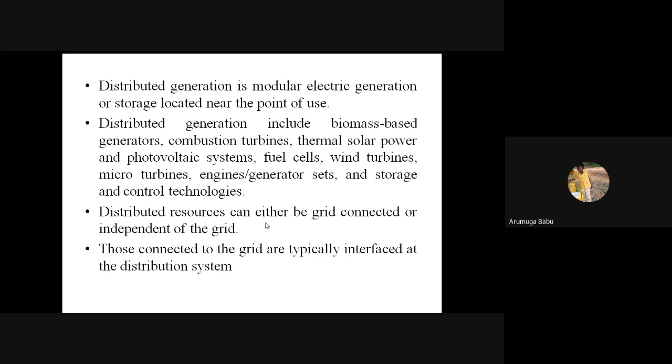So for example, if you have a solar power plant for your domestic application, you can generate electric power from the solar power system which is installed in your home. When there is no need of power in your house, you can deliver the power to the grid, and by using a bidirectional meter, you can have a tariff based on the power which you consumed and which you supplied to the grid.